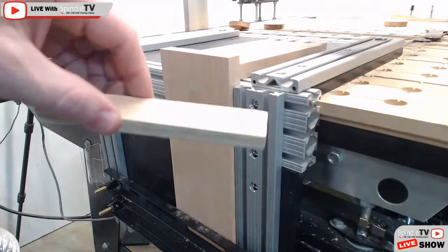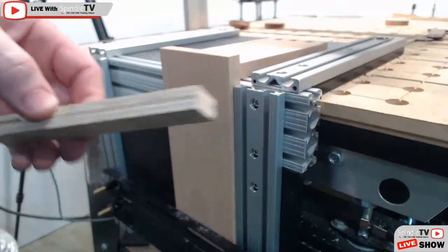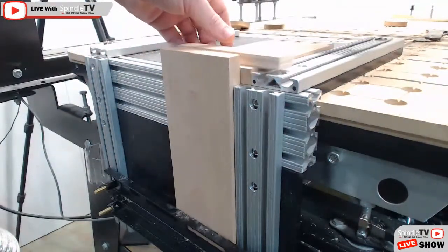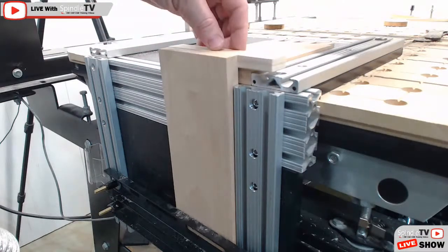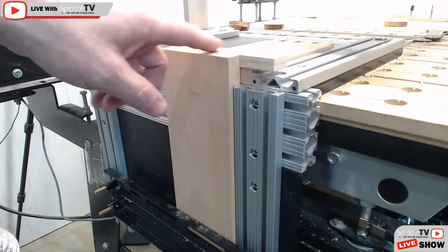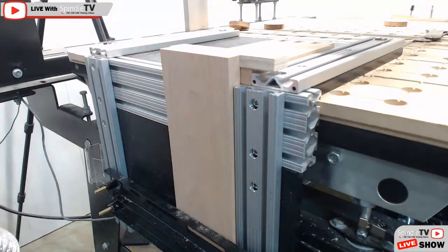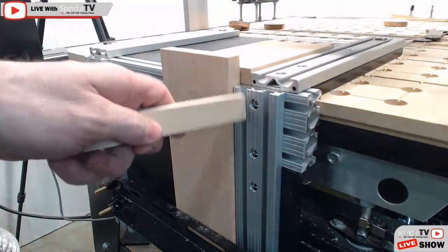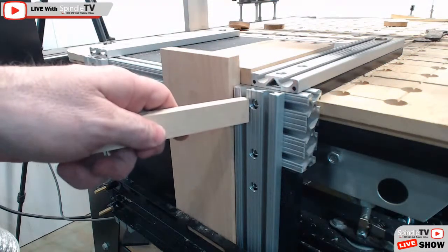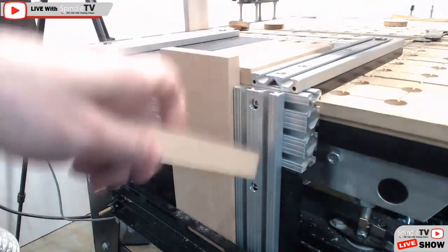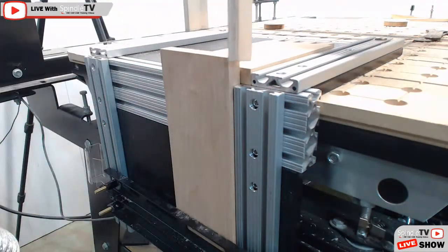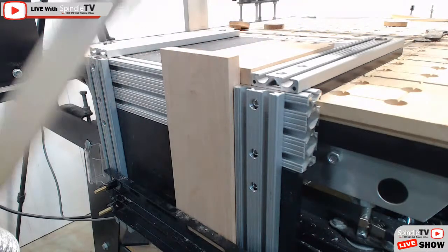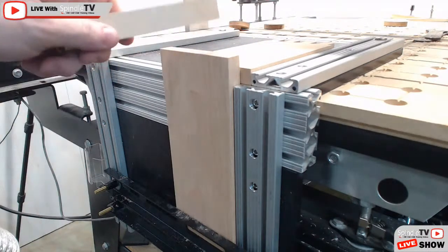So I've got just very simply a 1/2 inch scrap piece of material. I lay this horizontal board on here, my piece, and I just took this 1/2 inch piece and made sure that I was flush to the top there. And that's going to give me plenty of room for when I'm making cuts that I won't hit this fence here. This fence here, because of the offset, I've got this fence offset to the side. My bit will come right beside it and clear it. And that is key.